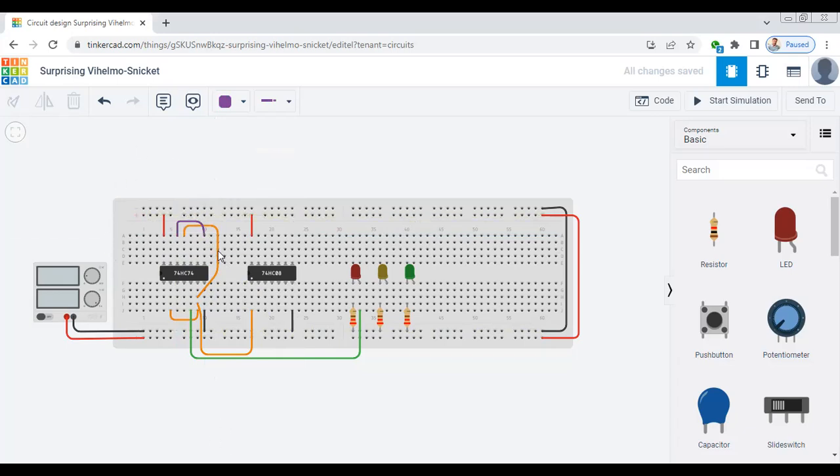After that we take the wire from in between the 12 and 8 number pin and connect that wire to the output as mentioned in the circuit diagram. So this combination we connect to the output, and for the output we are using the green color wire, this one.